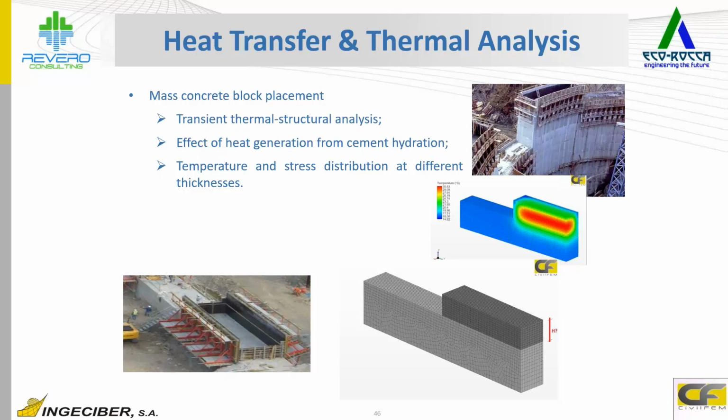We know that when pouring large amounts of concrete, a lot of heat is developed due to cement hydration, and then this heat will generate stresses on top of the stresses given by the loading of the structure itself. So we can do an analysis to see how pouring various amounts of concrete would generate stresses which can cause cracking of the concrete.